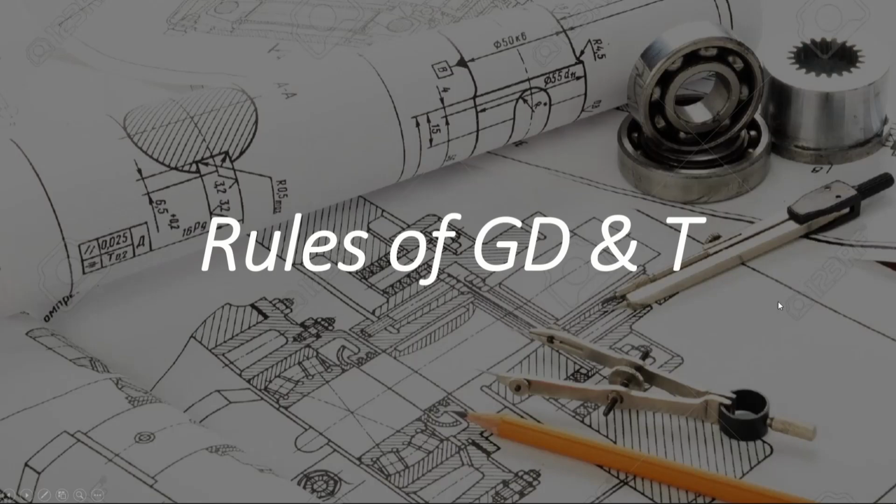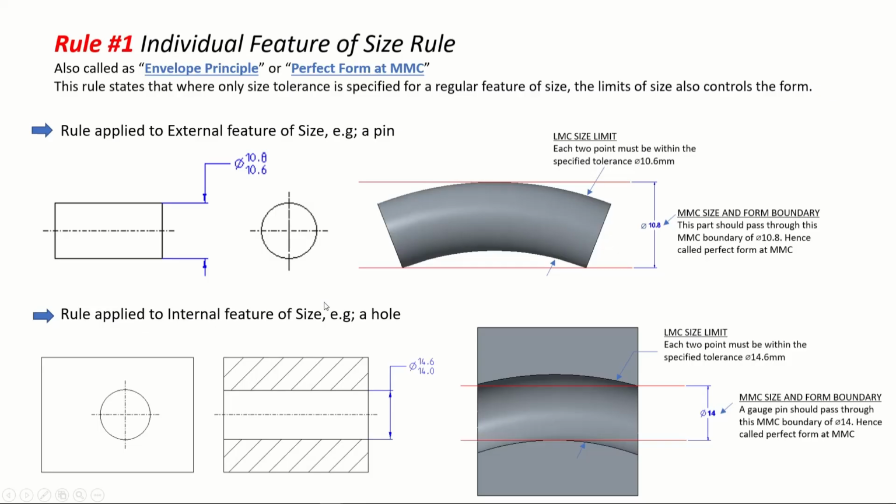This is very important actually. The first rule of GD&T is the individual feature of size rule. It is also called the envelope principle or perfect form at MMC. The second name is actually the best way to remember it. The first rule is perfect form at maximum material condition.